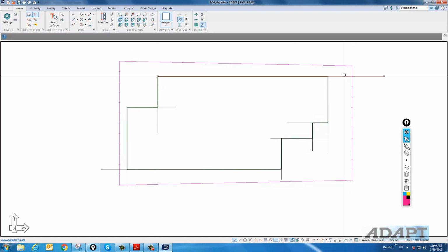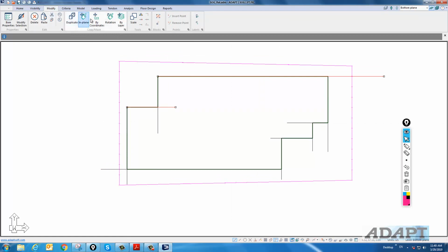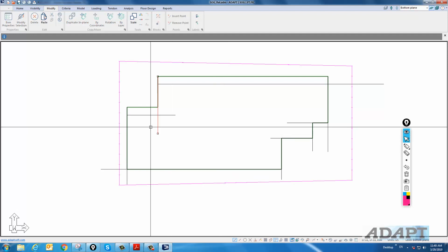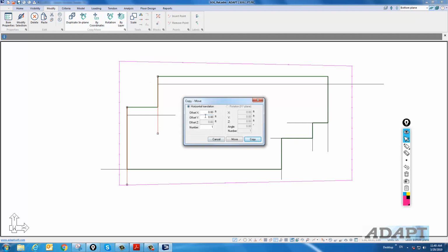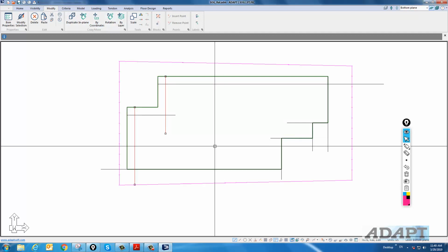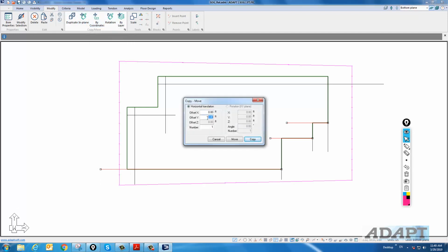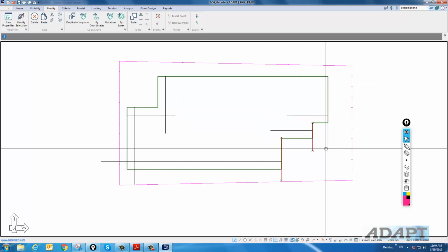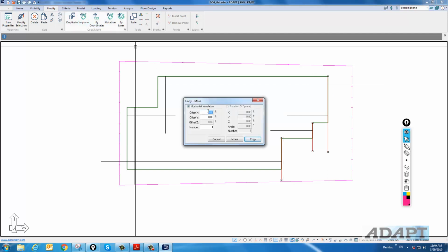Okay, and I'm going to offset these. So I'll offset this one, and we're going to go ahead under Modify. This is going to be -5 feet. We'll say Move. I'll take this one and this one. And this will be +5 feet. I'll move again. This is going to be a +5 in the Y, so we'll move that. And then finally we have the last edge that moves to the -X direction. So we have 4 movements of the different construction lines.